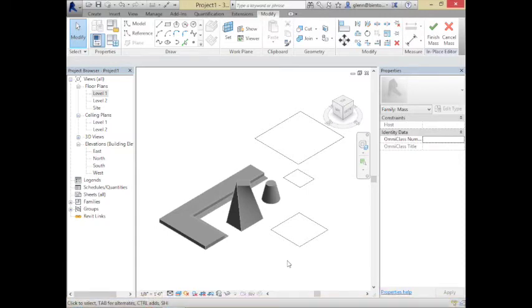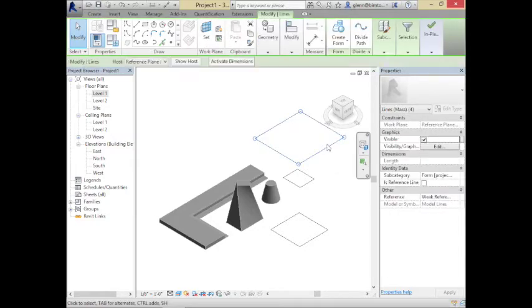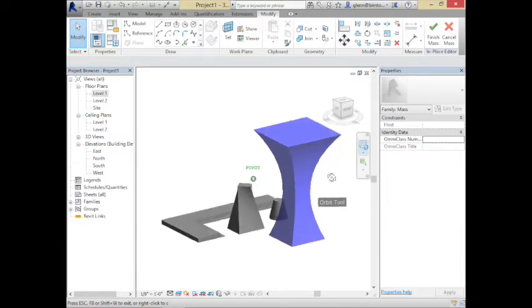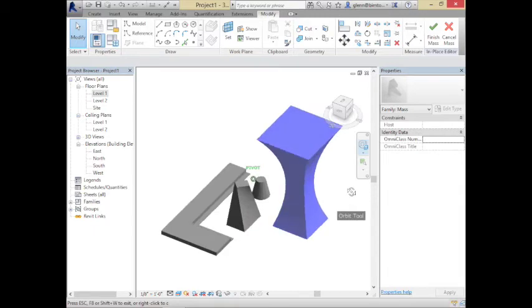So if I want to go through and actually join those 3 things and blend them all together, I can choose 1, 2, and 3. And then I should say I would like to create a form from them. Okay, it'll really make any arbitrary shape. So if you're used to working in a tool like Rhino, or there's a lot of different kind of CAD software tools that let you do this sort of thing. This is something called a Loft, where you can combine any sort of number of arbitrary shapes together and make a form out of them. But it's really a very powerful thing to do. So I can create something like that.